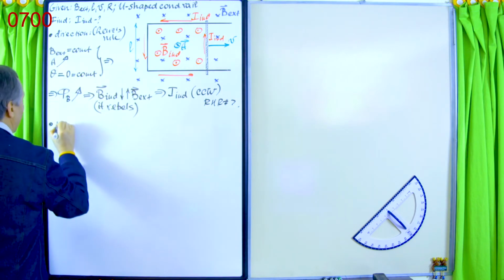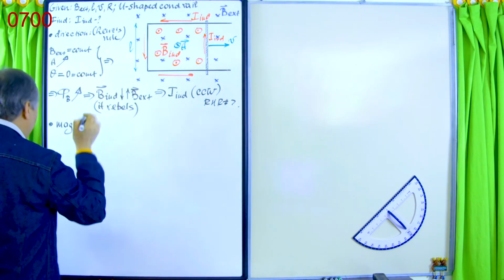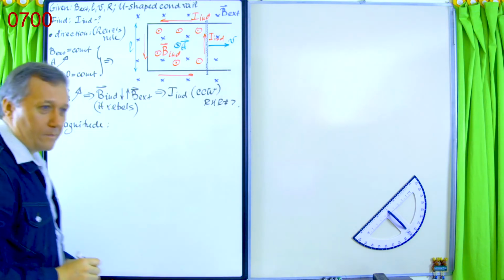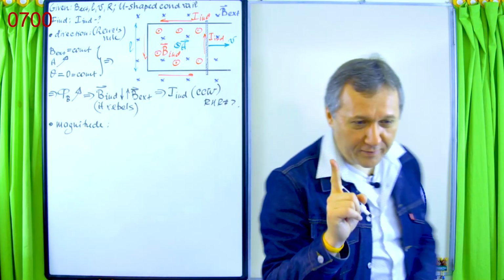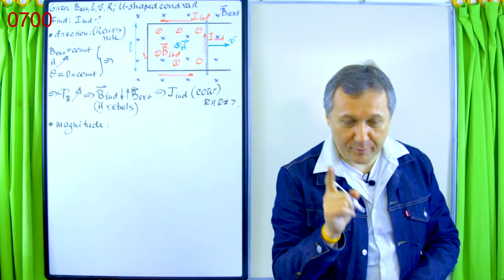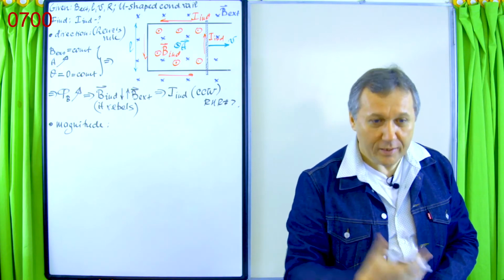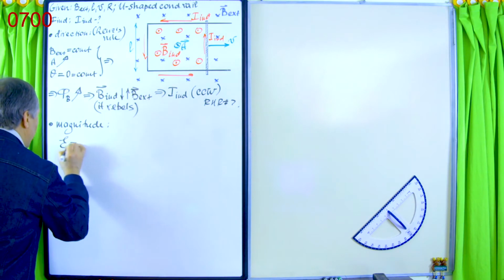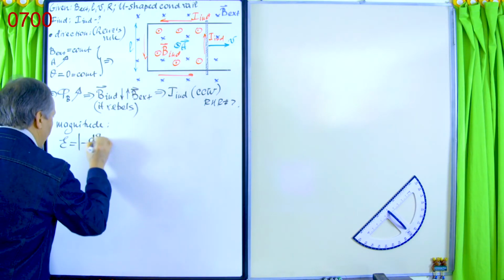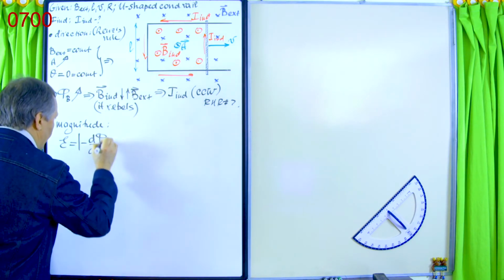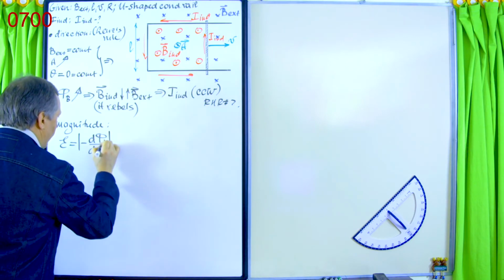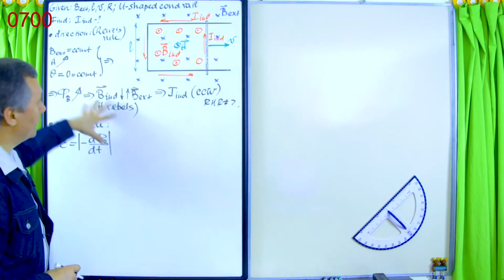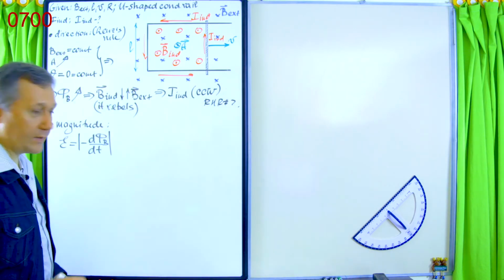Now the second bullet, magnitude of current. Magnitude. Right. But of course, before we can find the current, we need to find the value of EMF, because that's what we have in Faraday's law. EMF equals minus d phi over dt, right? And now, of course, I'm going to put this jacket, the absolute value, on the d phi over dt, right? Because again, minus gives us a direction. Now we already know the direction, so we can forget about that minus, right?